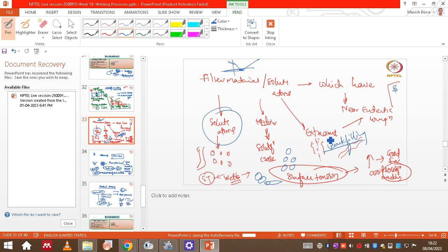So let's say, in another way, if we consider iron, sulfur generally reacts with the iron and forms iron sulfides, and that will form low melting phases present at the interfaces or interdendritic region, right? So to compensate for that effect, we should add a certain amount of manganese.